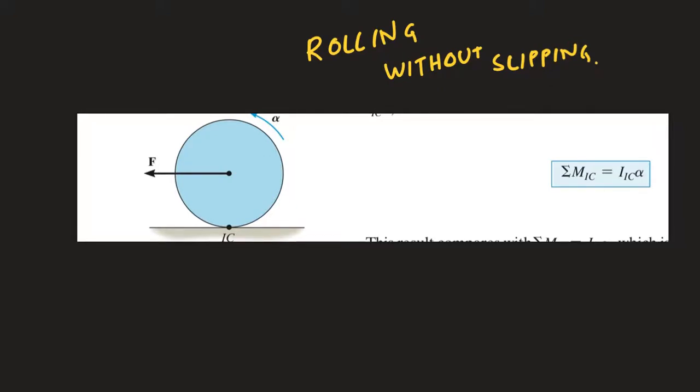Given that, using the concept of instantaneous center, this is called the instantaneous center of zero velocity, because this point is having a zero velocity for the time being. So using this concept, for that particular instant, or momentarily, I can assume that my disk is pivoted about this point, for that particular instant alone.